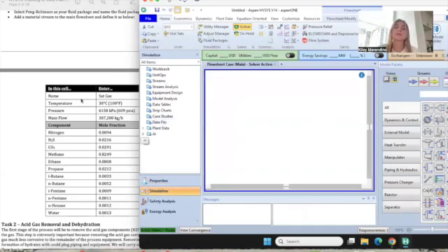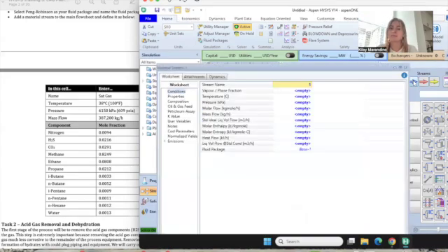The first thing that we're going to want to do is create a material stream. You can come over here to your model palette. This is where you're going to find all of your unit ops and create new streams. The blue arrows are material streams, red are energy, and yellow are power. So we're going to start off with a material stream. You can double click it. It'll create a material stream and you'll be able to edit it.